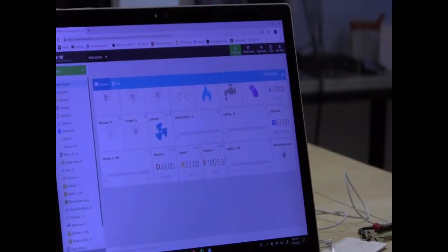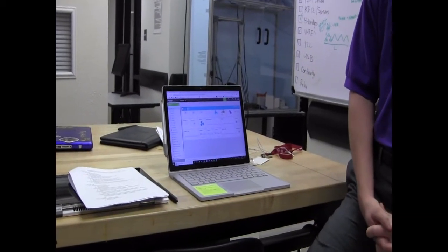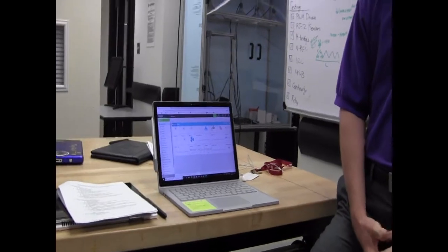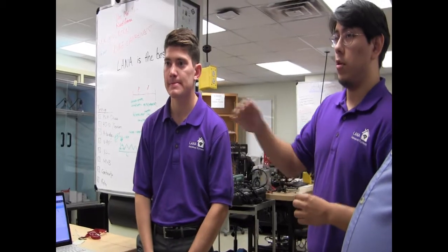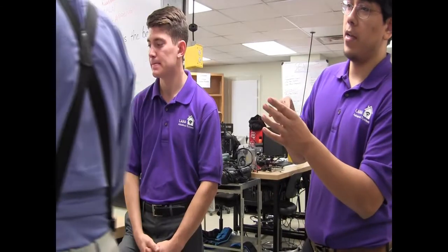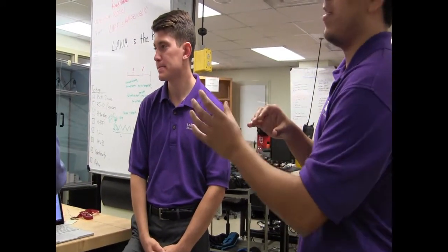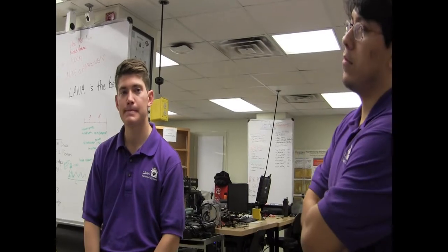How can you fix that? It might be the location of the PIR sensor and the location of the flag. What I can do is, I'm sending data in 2 sets. One of them doesn't include the motion. So if I include the motion in both sets of data, like I do with the temperature set point, you'll get it no later than 5 seconds. But in my case, if it misses that one set, it'll have to wait 5 seconds and then 5 seconds to get to the other side. So that's why we missed it in this case. And it's not a matter of the flag waving.